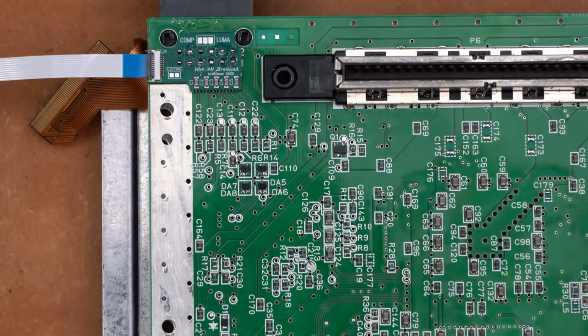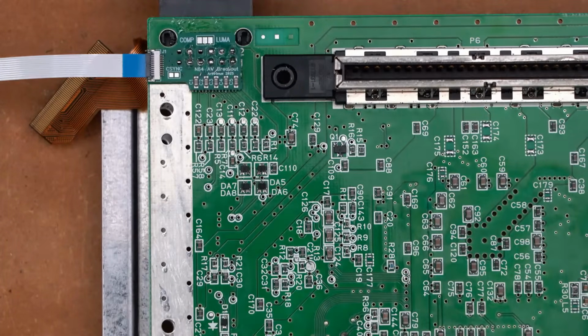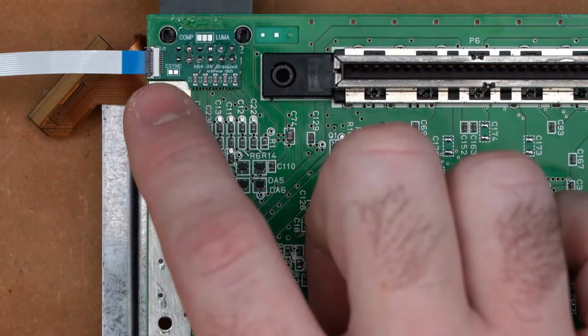The C-Sync signal that the N64 DAC generates is valid for this modded RGB signal. So it's really up to you whether or not you want to do this. For these early models, I will just leave the resistors in place and leave the C-Sync jumper open.